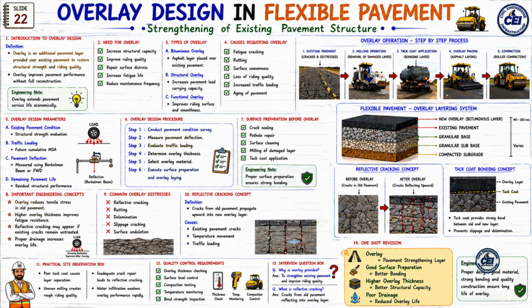Now let us look at the fourth topic. Four causes requiring overlay. Why is there a need to provide overlay? Fatigue cracking, rutting, surface unevenness, loss of riding quality, increased traffic loading, aging of pavement. And as the traffic loading increases, the existing pavement starts becoming weak.